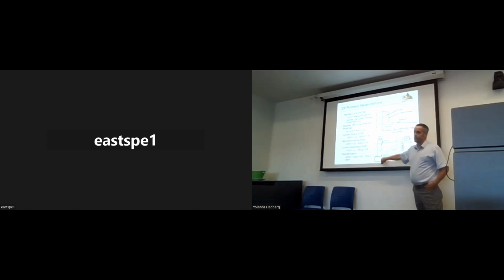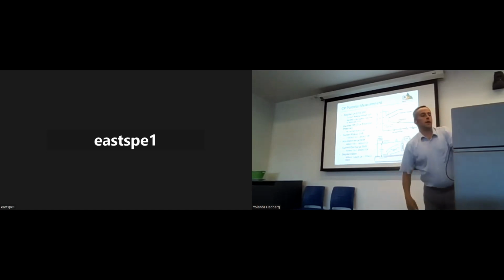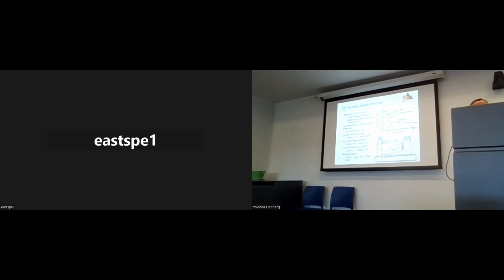Here's my pipeline that I'm trying to take a potential on. When the rectifier is on, there's current flowing through the soil to our pipe, and it's that current flowing through the soil that gets in between our measurement circuit. So we have to interrupt our rectifier to get rid of that error, which gives the on potential and the off polarized true potential.